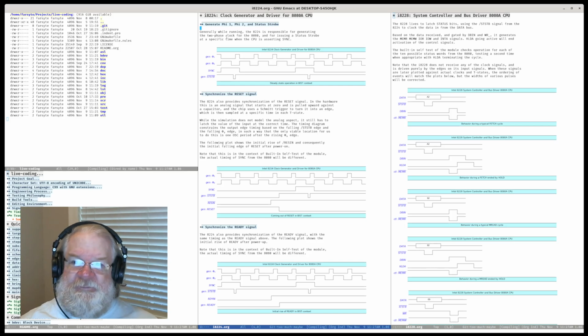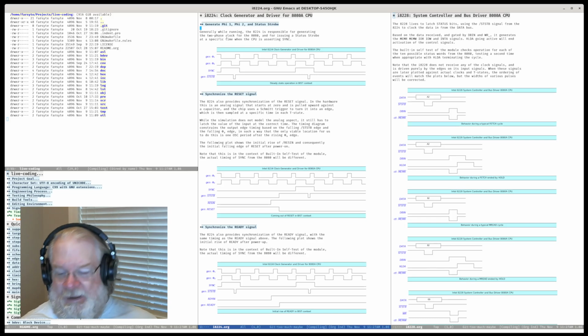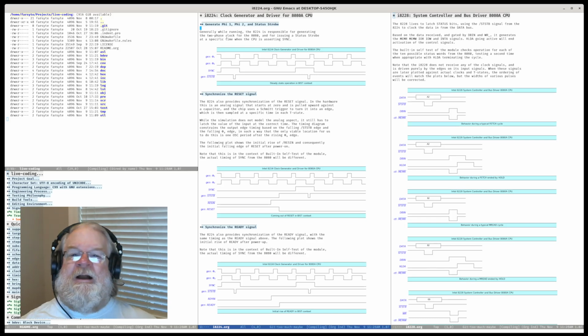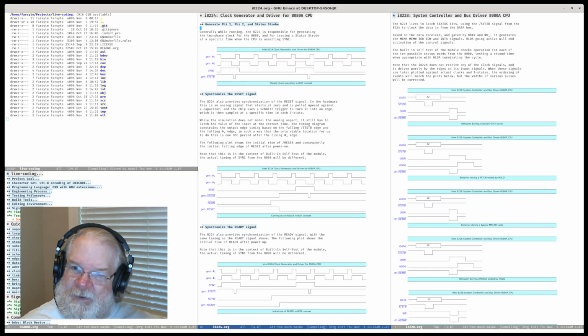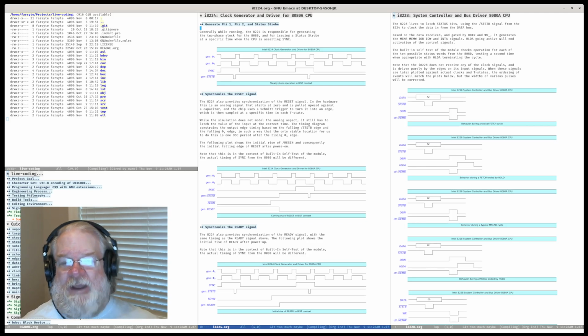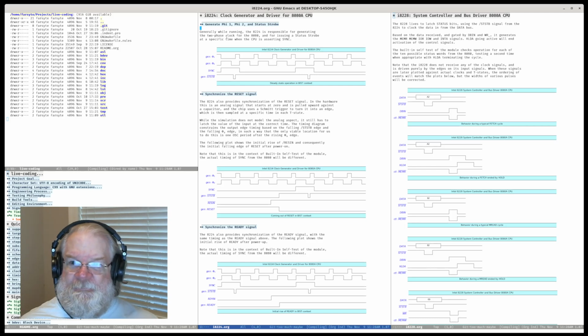And at the root of the simulation, there's somebody whose entire job is to set the clock high and get a rising edge of the clock, and that percolates through the system. And then it sets the clock low, and that percolates through the system with a falling edge. So everything happens edge triggered. And what you do is you say, I have this function I want to run.